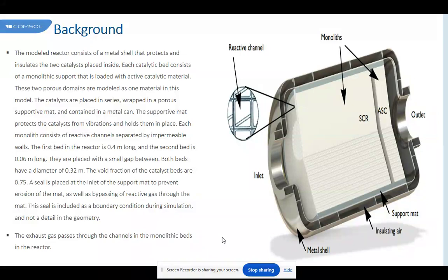Constant physical properties and uniform channel cross-section are assumed. Next, the steady-state bifurcation diagram. Before we present numerical simulations, we analyze the effect of the solid conduction on the steady-state behavior of the monolith using simplified versions of the above general model. We consider first the limiting case of zero solid conduction and uniform catalyst activity. Further, we make the assumption of constant values for the transport coefficients, using asymptotic values for the transport coefficients. We use a positive exponential approximation and neglect washcoat diffusion limitations with this assumption.